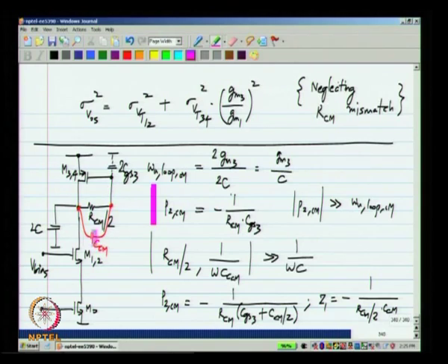There are many ways to calculate the stability of this. Okay. We have seen circuits like this on other occasions, like when you calculate the frequency response of a common source amplifier, we have a similar circuit with a capacitance from the drain to ground, capacitance from the gate to ground, and a capacitance between gate and drain. Okay. And we know where the poles are in such a situation, there will be pole splitting and so on. So, and then we can calculate what the closed loop poles will be and whether the circuit is stable or not. And a simple feedback circuit like this is almost guaranteed to be stable. You do not have to work too hard to make it stable or to eliminate ringing and things like that. Okay.